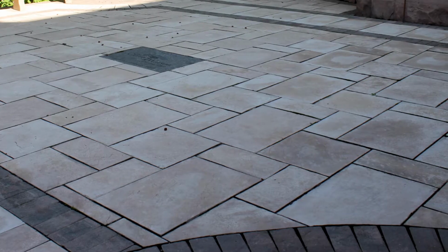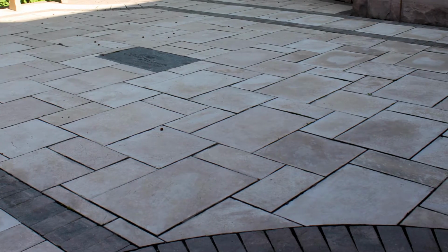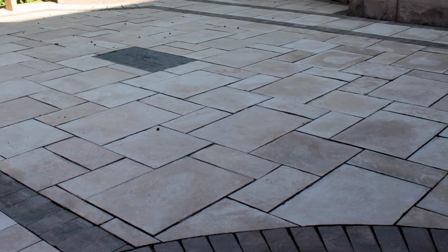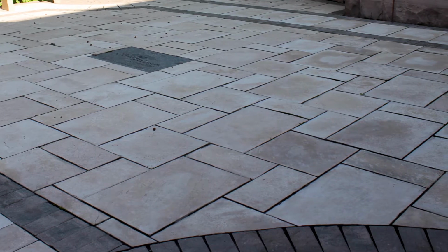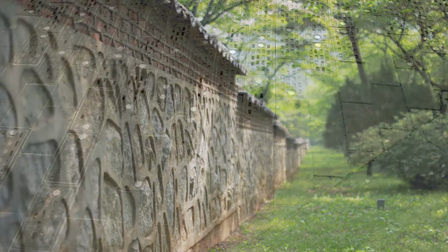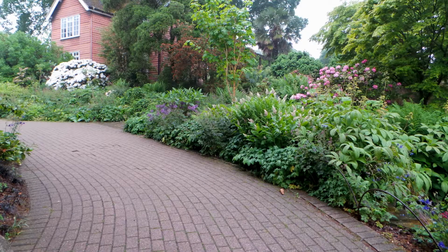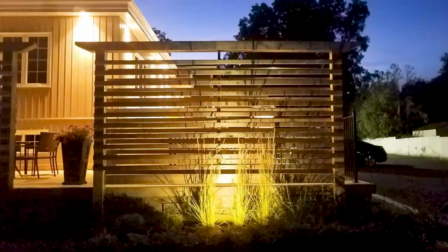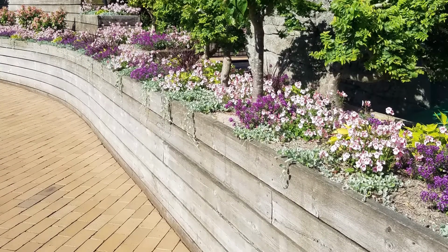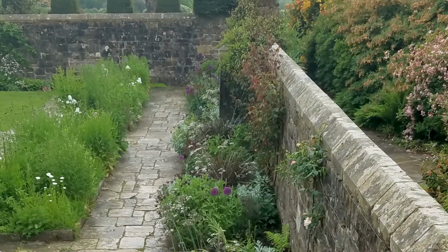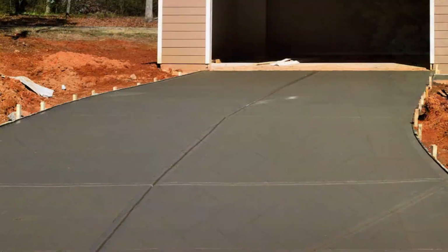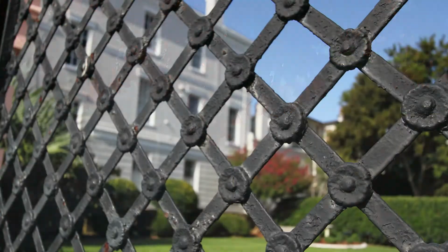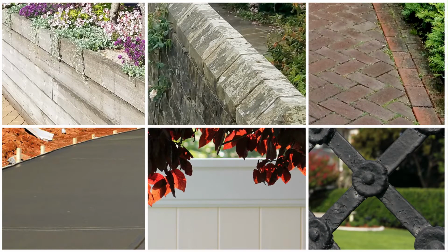When we discuss the term hardscape, we are referring to any part of the installation that involves building something. This can include walls, sidewalks, driveways, stairs, patios, arbors, and decks and landscape lighting, to name a few. And hardscapes can be made of wood, rock or stone, man-made pavers, concrete, plastic, or metal, and are generally intended to be permanent parts of the landscape.